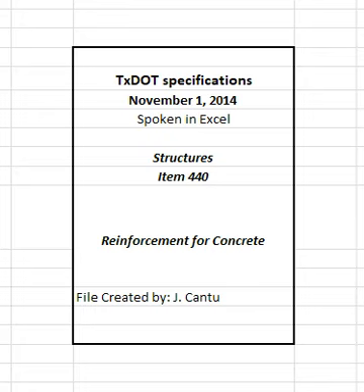Clean mortar, mud, dirt, debris, oil, and other foreign material from the reinforcement before concrete placement. Do not place concrete until authorized. Stop placement until corrective measures are taken if reinforcement is not adequately supported or tied to resist settlement, reinforcement is floating upward, truss bars are overturning, or movement is detected in any direction during concrete placement.